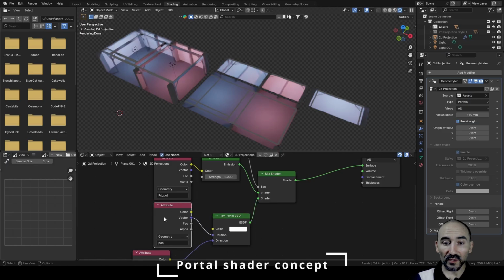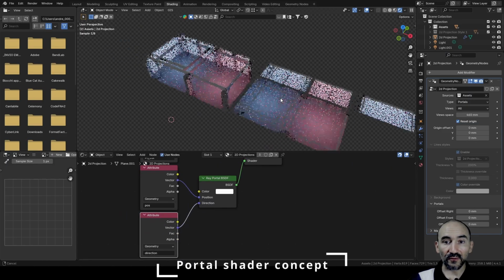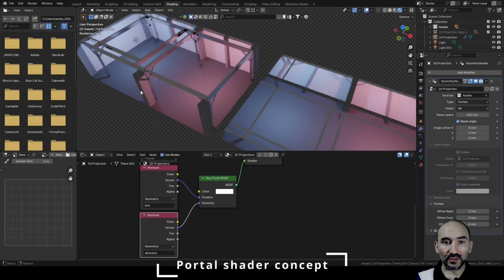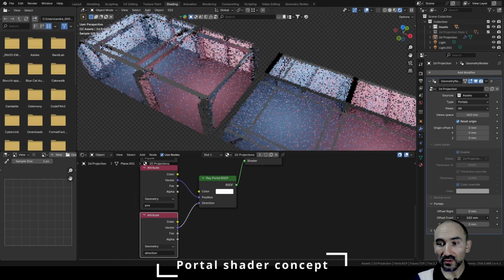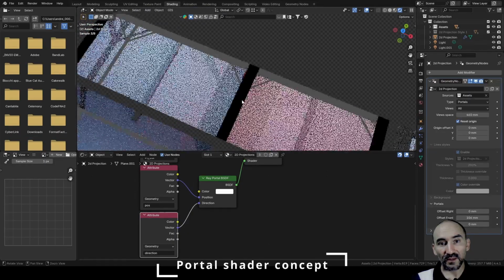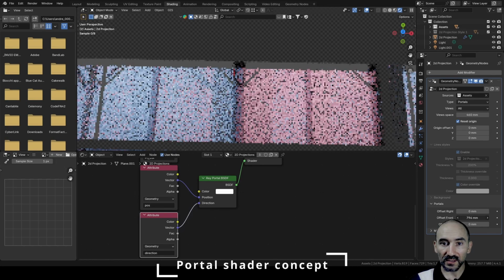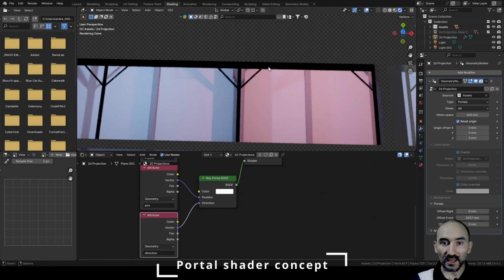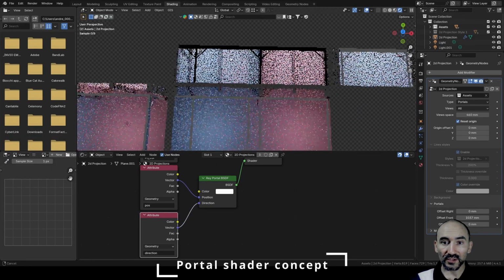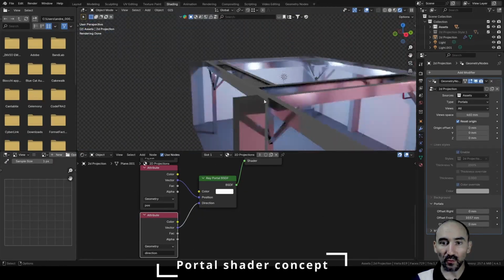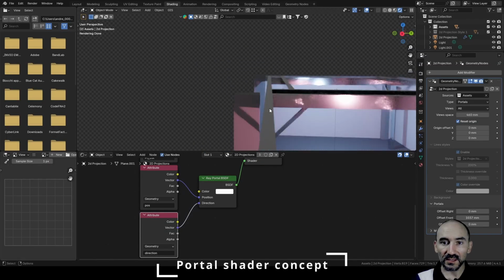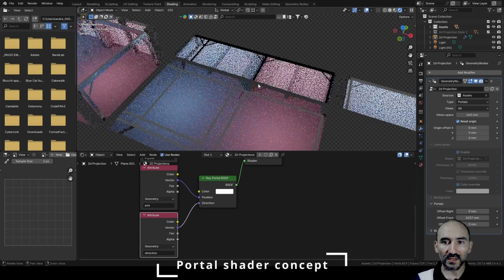And now if I want to cut this structure, going for example inside this collection through the positive Y axis, I just need to increase the offset of the front view, okay, this front view, and as I increase this front view, you can start to see black values near the columns here. And if I increase and increase and increase, you can see near 1 meter the cutting of the metal structure of this collection of assets. Okay, as you can see here, near 1 meter we have the cutting of this section, and this is the advantage of this cutting section.